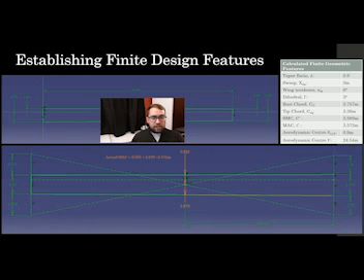Wing sweep would cost lift efficiency from reduced aspect ratio and once again increase the risk of tip stalling. It's unnecessary for a HAL UAV. So the quarter chord line will remain at 0 degree sweep angle across the span. Wing dihedral will be 3 degrees due to benchmarking.